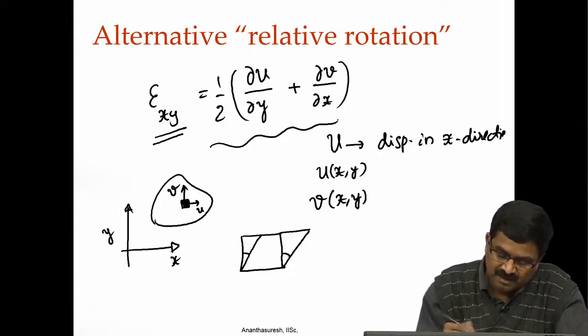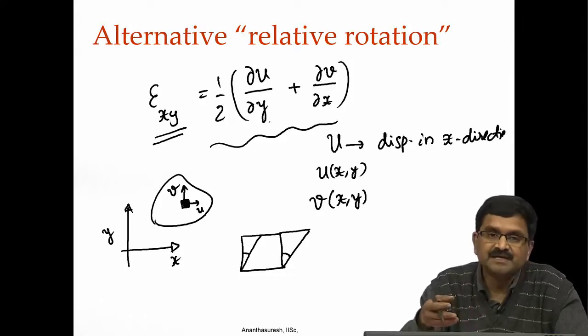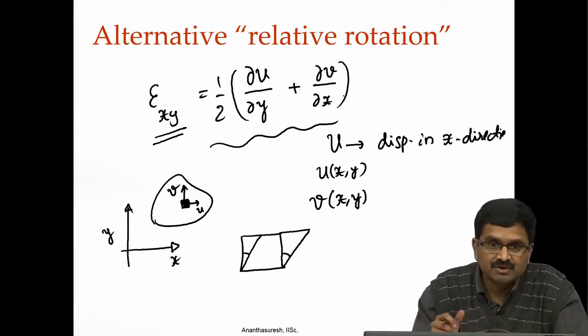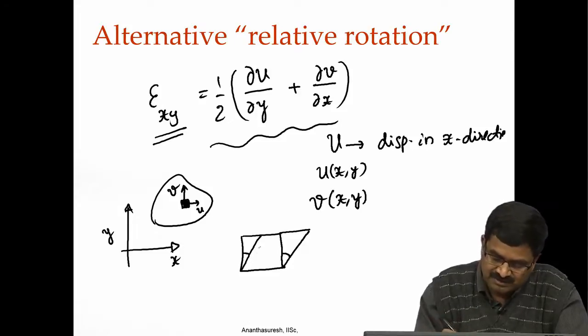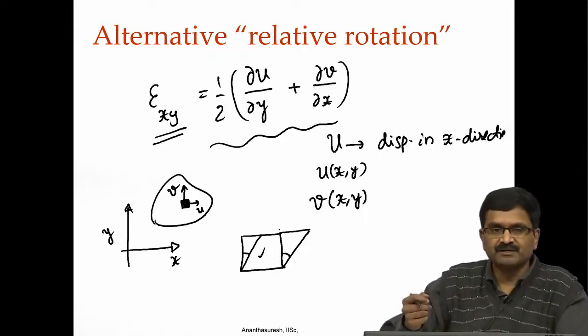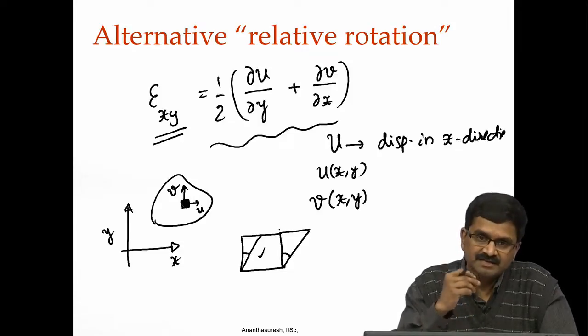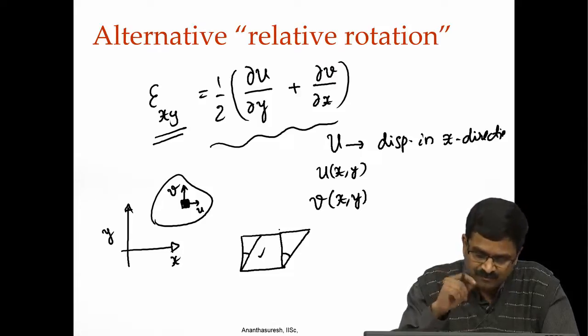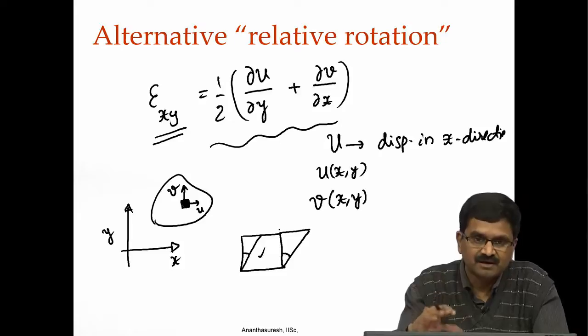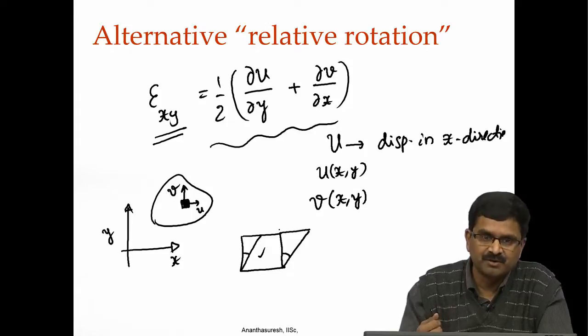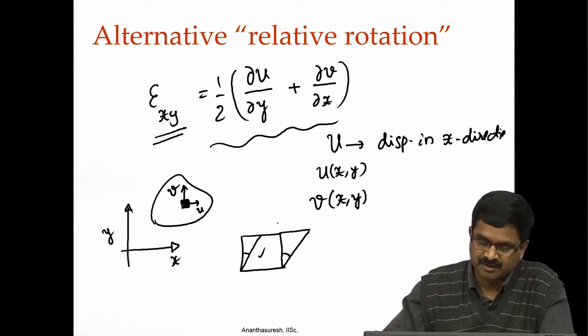If you take this for every element and basically integrate it over the entire domain, this is a measure of relative rotation in a way, how much the element is distorting. You can take how much shear is there with this element and the next one, take the difference and quantify rather than going for the vectors. This can also be done, and it gives similar results, meaning that it does avoid hinges, not always, but with tuning you can make it work. It is still quite a difficult formulation to implement, but that is there, and there is no other idea that directly tackles this problem. People have tried a lot of methods to avoid these one node hinges, but containing the relative rotation, restraining it, seems to be the best way.